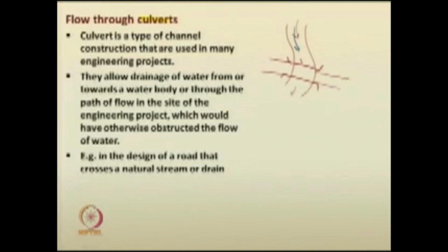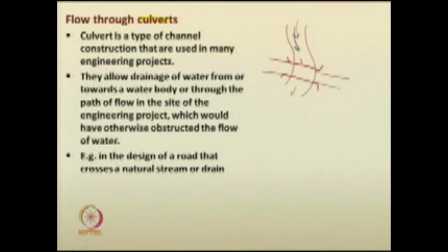So, it is advisable that you do not block such natural drainage paths. Therefore, you can get enough quantity of water in your water resources or reservoirs. Say a road is being built like this.